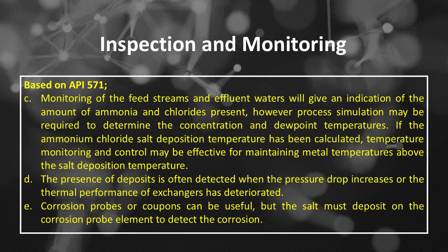D, the presence of deposits is often detected when the pressure drop increases or the thermal performance of exchangers has deteriorated. E, corrosion probes or coupons can be useful, but the salt must deposit on the corrosion probe element to detect the corrosion.